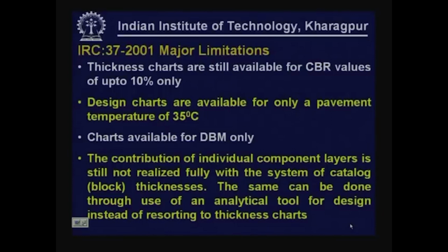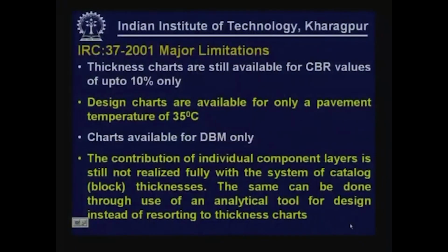The contribution of individual component layers is still not realized fully with the system of catalog or block thicknesses. What the chart gives you is only the total thickness, how this has to be split into different component layers. If more surface thickness or more base thickness is provided, what will be the effect on the performance cannot be explained using these charts. Of course, the same can be done through the use of an analytical tool for design instead of resorting to thickness charts.